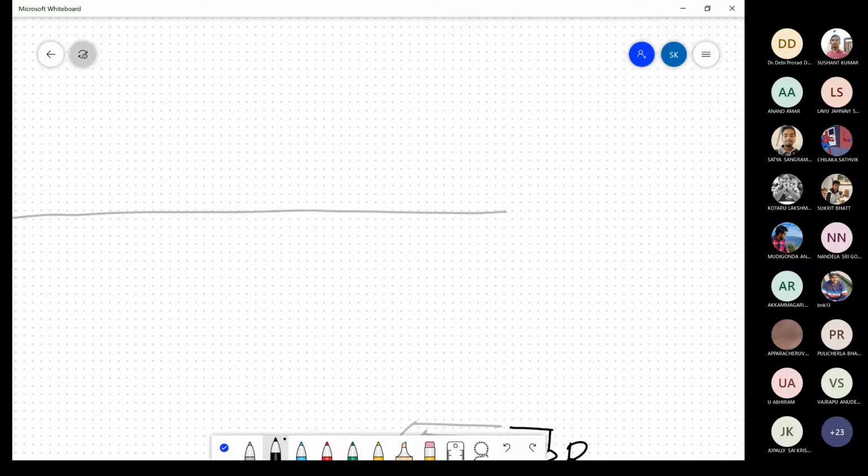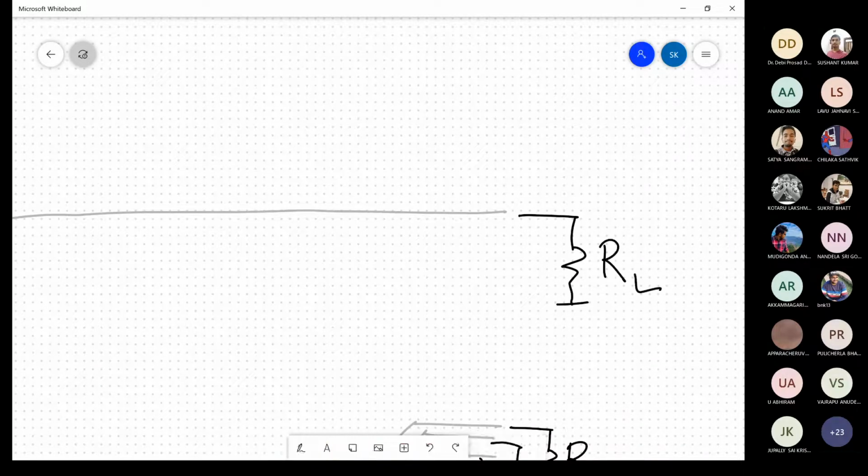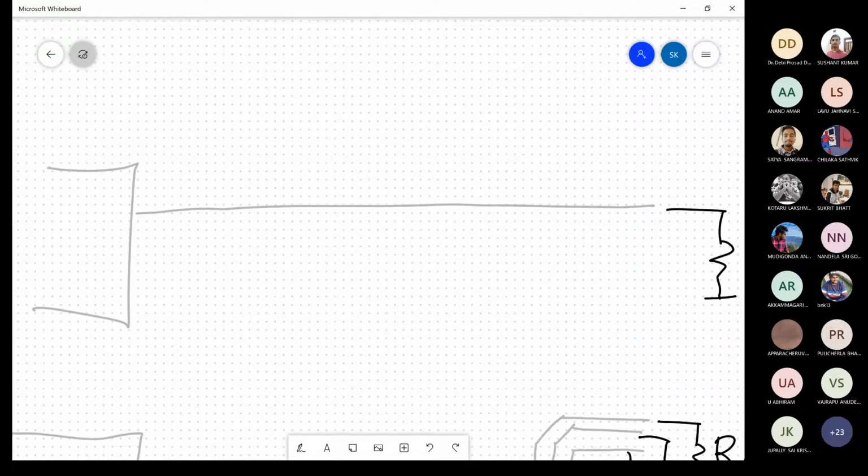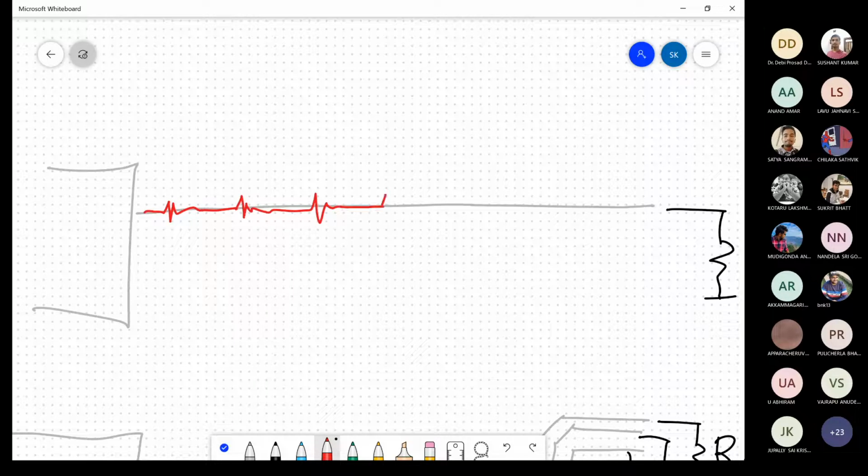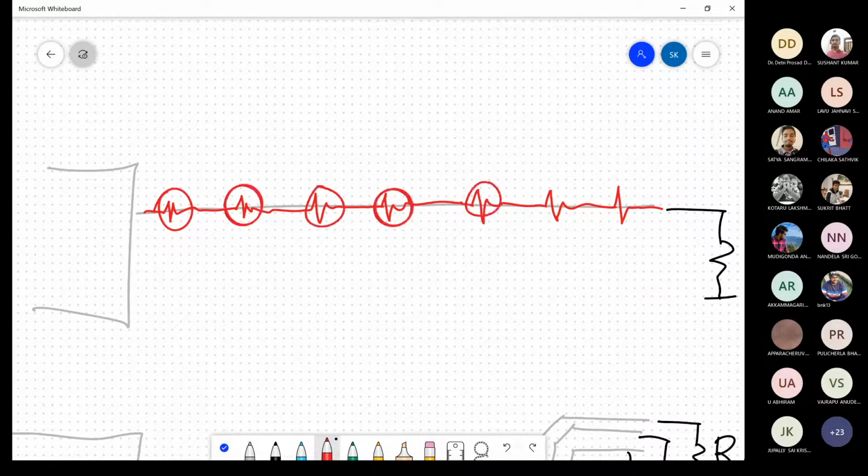But if I draw one of those wires, there is a RL here. And you will be able to take this long segment of gray and change it into, let's say, one resistance, then another resistance, then another resistance. I mean, that distributed resistance of this wire is going to look like this. And so I can lump it, and instead of having a distributed resistance along the wire per running centimeter of the wire, I can say, let me simulate that resistance by so many resistances. That's one thing, the resistance part of it.